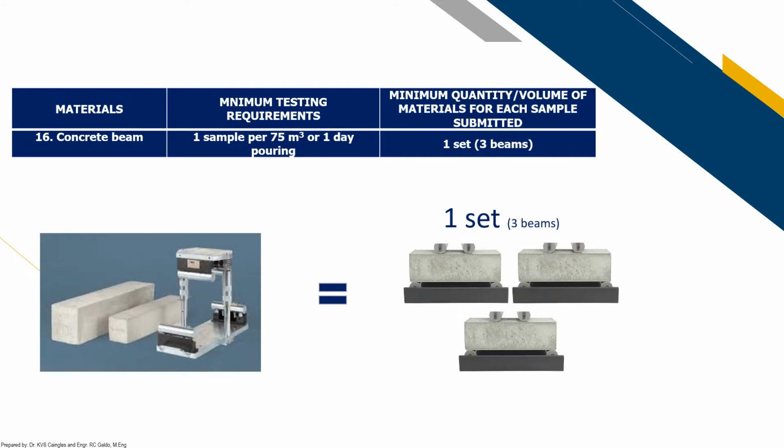Okay, concrete beam. So same gihapon siya no og minimum testing requirement, one sample per 75 cubic meters, and then one set gihapon, and then ang one set is three kabuok, three beams na siya. No? So usually ang kining concrete beam is for testing in flexure. So when do you use concrete beam sample? It is diha sa kanang mga pagbuhos nimo sa roadway.